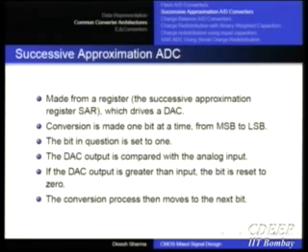So it's only when you want conversion rates of that order that you would consider a flash, or I'm assuming that is with a reasonable resolution, or the amount of resolution that you want is very small. In that case, that's okay. You could in fact even go to higher frequencies at that time. But generally it makes sense to go for flash converters only when you are talking of those speeds.